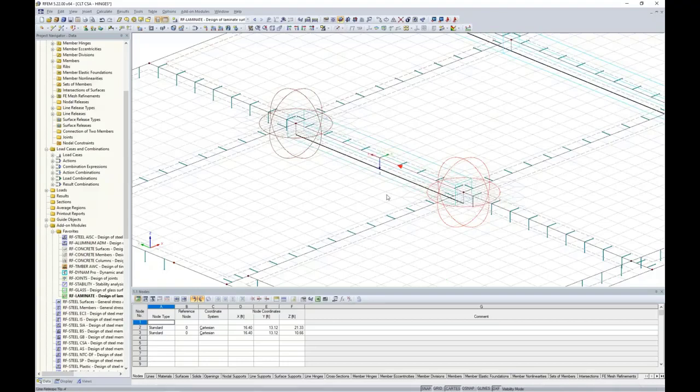Now this is not going to take care of our singularity problem, but what it is going to do is make this high stress location available to us in a much smaller location than rather us using the 1 foot width of the global FE mesh settings. So we're isolating the issue into a smaller area.